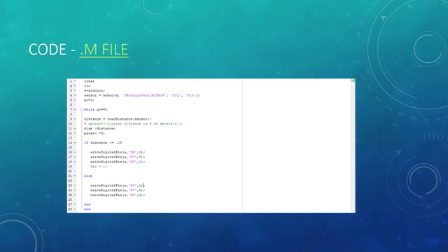And next we have our if statement for the distance being less than or equal to 0.15 meters. And in that case, we have the red digital pin receiving a signal while the other two are not. We commented out the go equals 1 because it was causing some issues to where if we reached that red readout on the LED, it would terminate the whole program. So we just decided to remove that so that we could go between green and red.